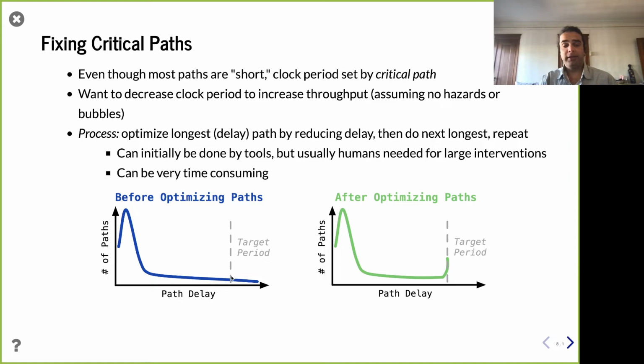And so the ones that are longer than your target clock frequency, well, those are the ones you need to fix, right? Because let's say you're shooting for a certain clock period, like, we're going to fit our performance budget, or better yet, performance budget meeting a certain energy budget if we're running at this period, right? If we have this clock. And so these paths are longer. Well, those are reasons why you can't run at that frequency.